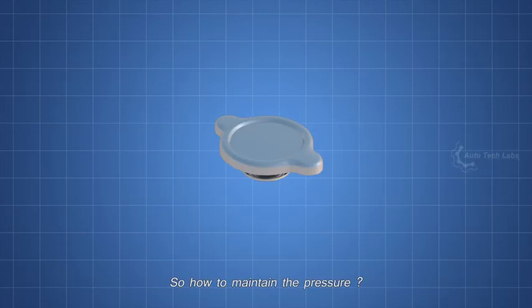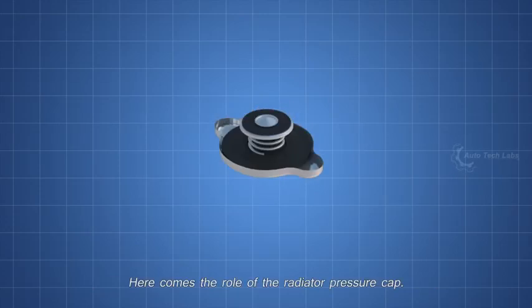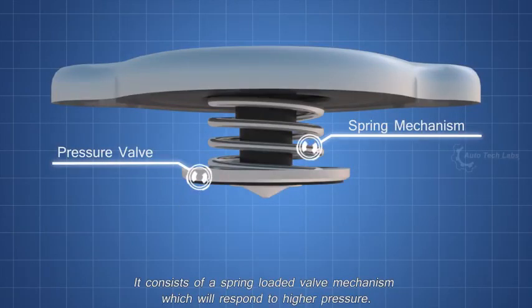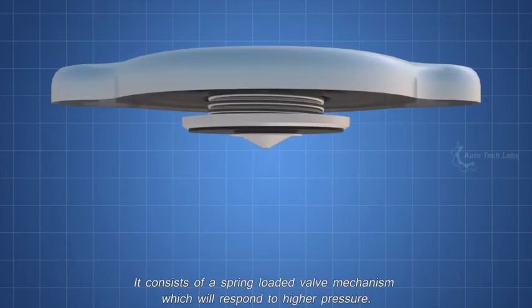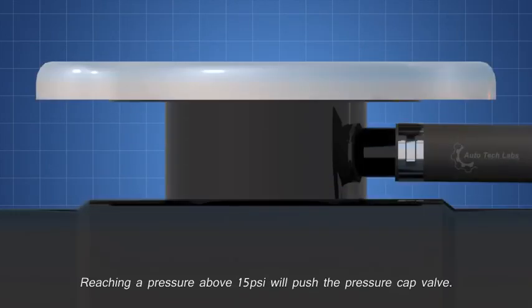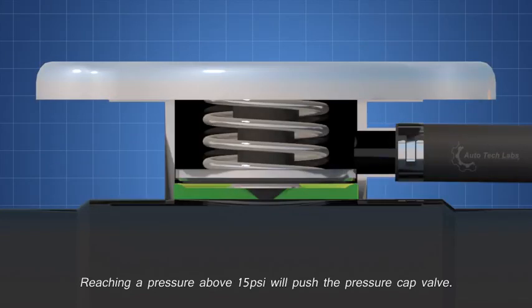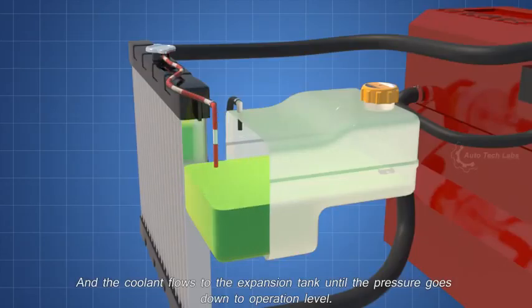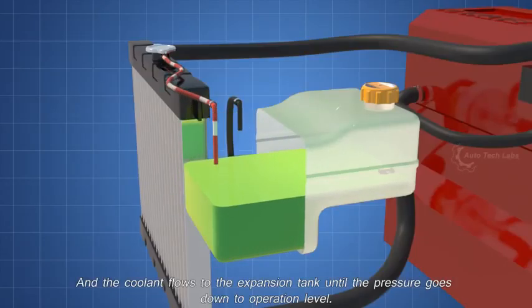So, how to maintain the pressure? Here comes the role of the radiator pressure cap. It consists of a spring-loaded valve mechanism, which will respond to higher pressure. Reaching a pressure above 15 psi will push the pressure cap valve open, and the coolant flows to the expansion tank until the pressure goes down to operating level.